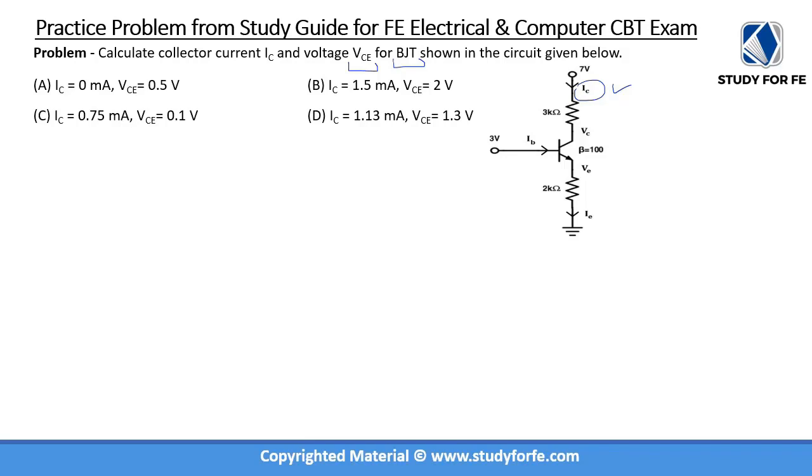They are also known as the Q point. Once you establish the Q point, you also know the mode of operation of the BJT, or the MOSFET. Because in order to establish what VCE and IC are, you first have to determine the state of operation. We will go through all of the 4 or 5 steps that I mentioned earlier in the lecture systematically in order to analyze this circuit.